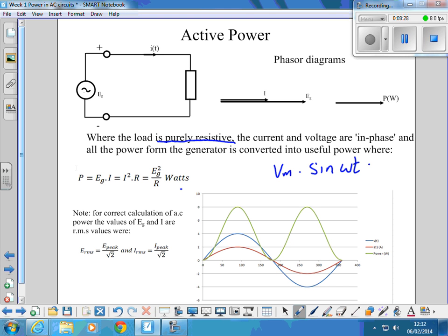It's the effective DC value, yeah. I'll put it on another slide in a minute, Joe, all right? But you're correct. It's the equivalent DC value of that AC sine wave. It is only √2 for a perfect sine wave. If the waveform was a different shape, it wouldn't be E peak over √2. It would be a different formula for that, okay?